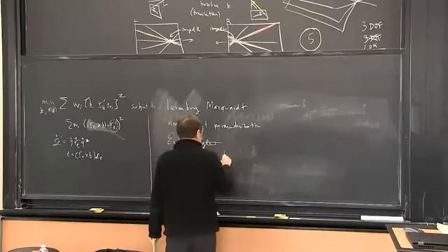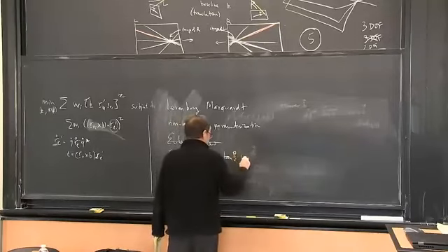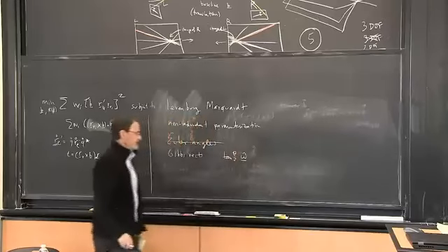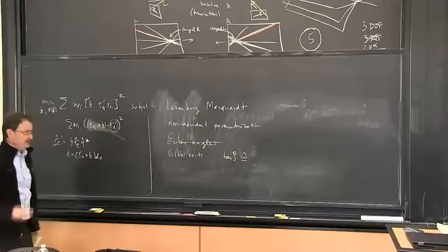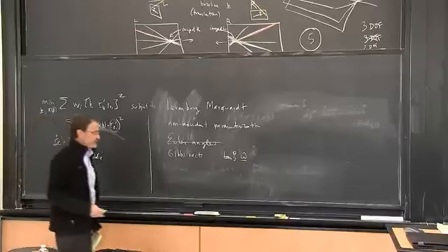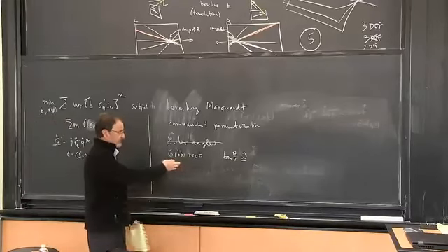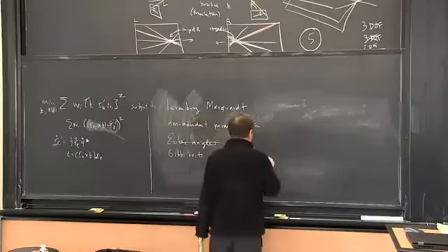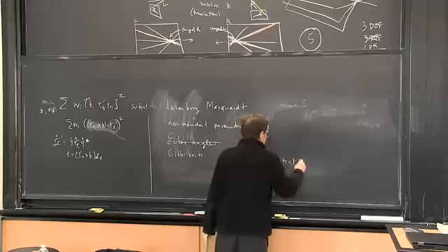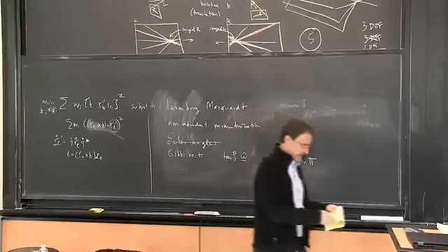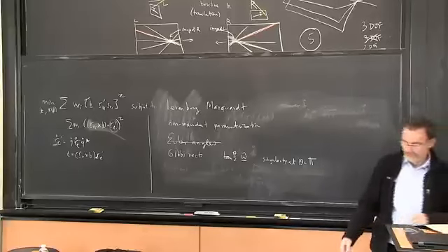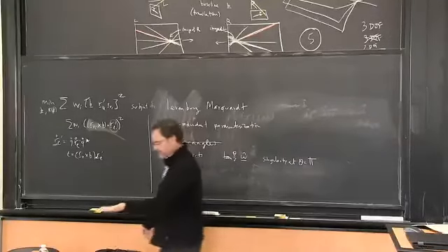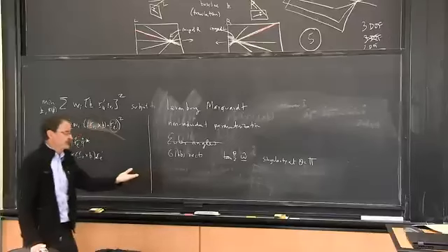So the Gibbs vector is tan theta over 2 times omega hat, where omega hat is the unit vector in the axis direction. And this is obviously a vector. It has 3 numbers, 3 degrees of freedom. And unfortunately, it has a singularity at theta equals pi.